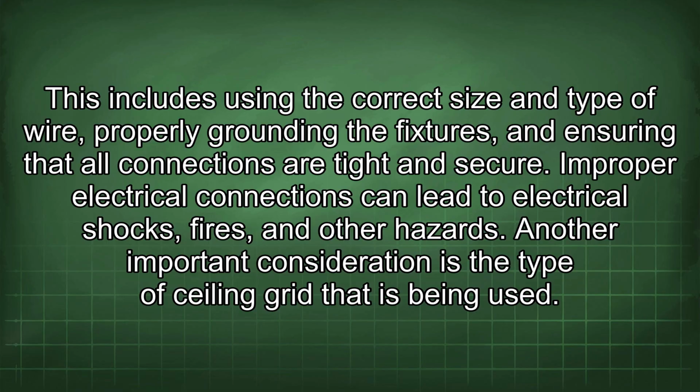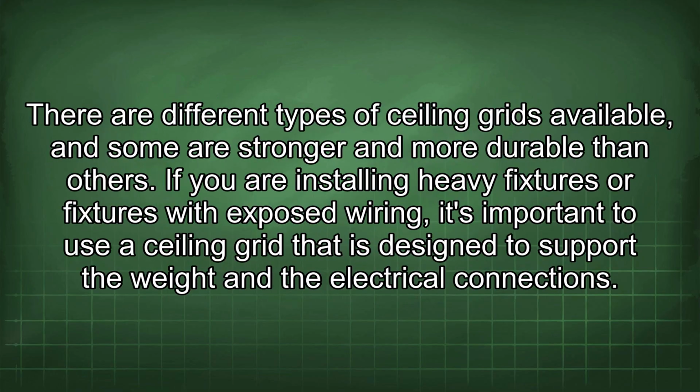Another important consideration is the type of ceiling grid that is being used. There are different types of ceiling grids available, and some are stronger and more durable than others. If you are installing heavy fixtures or fixtures with exposed wiring, it's important to use a ceiling grid that is designed to support the weight and the electrical connections.